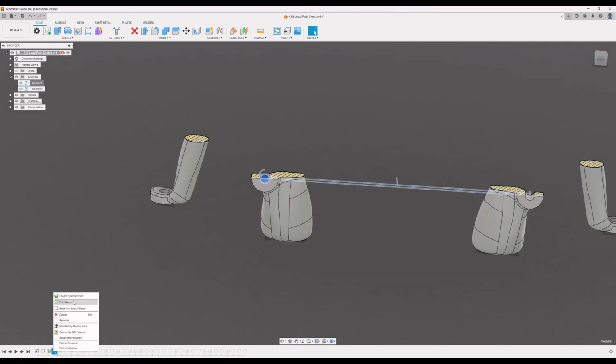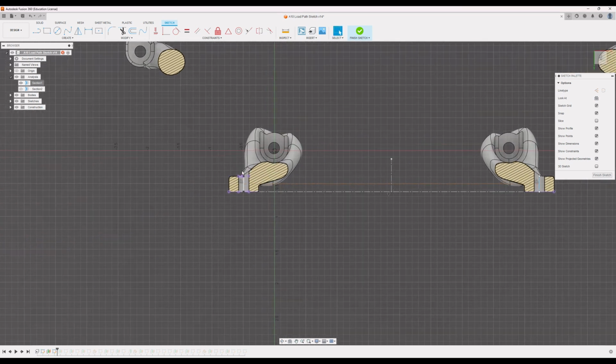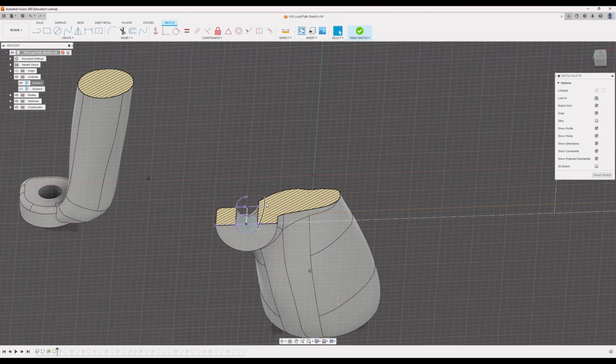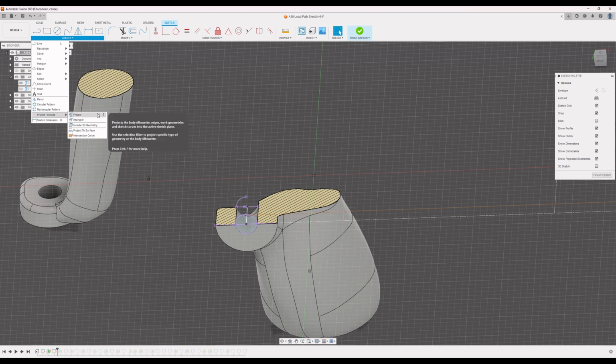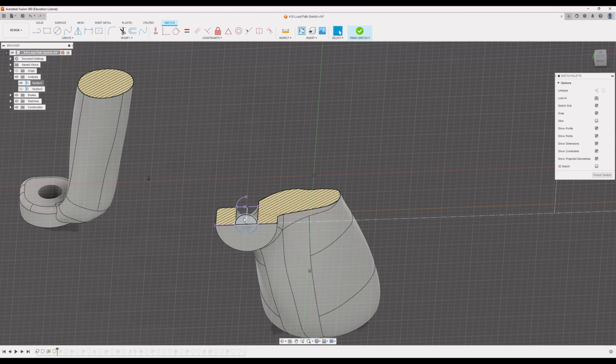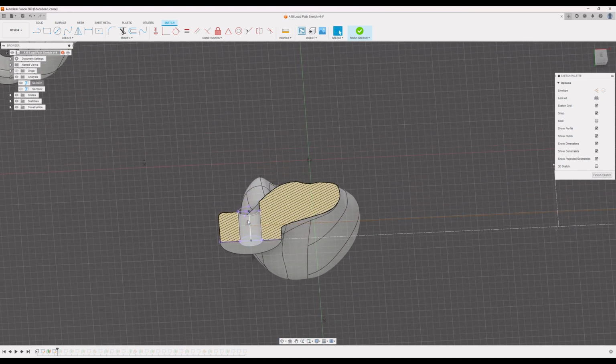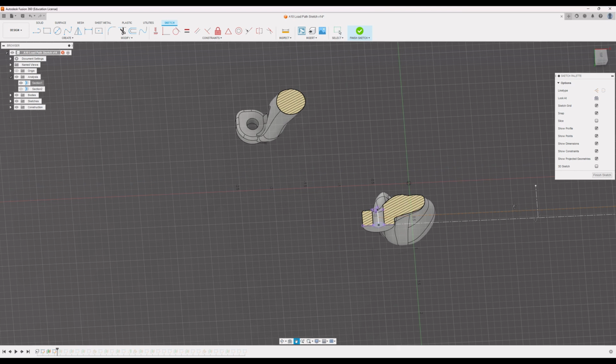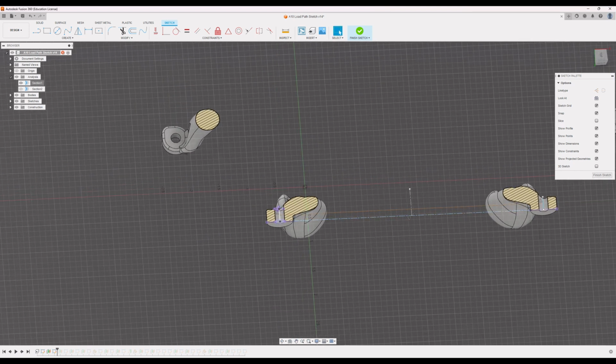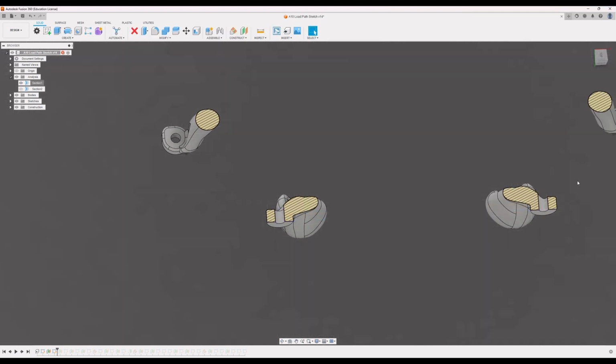So one of the best ways that I've found to do it is to use what's called the projection tool, and this lets you project existing geometry onto your sketch plane. This is really useful in allowing us to just really quickly find the centers of lines or the center points of holes. And so here we can go ahead and model the center of that hole, and later we can connect it to the line of force running up through the leg.